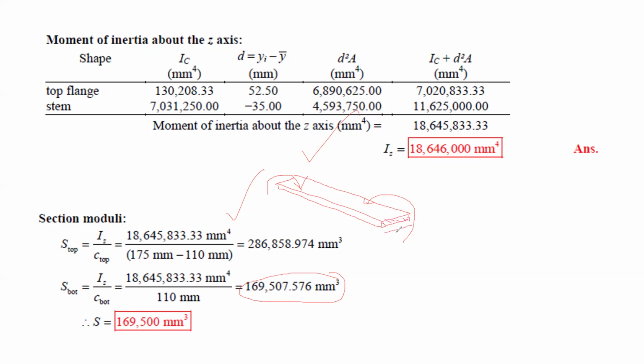In this cross section, this is B and this is height, right? When you calculate 1/12 B H cubed, this value is small, so you get a lower number. But when I use the same steel ruler in the vertical configuration and try to bend it, it will not bend, or might bend but not very easily, because the value of H is higher and B is small. So when you calculate 1/12 B H cubed, this value is higher, and technically the value of I is a higher number.